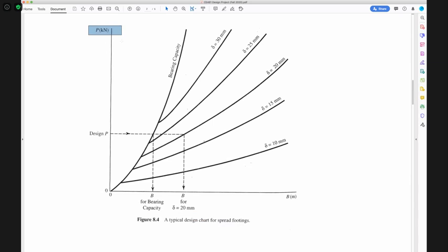We have a load for the foundation and the size that's required to hold that load. And we go through and solve that for bearing capacity. I mentioned in the problem statement just about a page ago that you'll want 10 data points to make this curve, the bearing capacity curve. So you'll come in with different loads around your design P. You know what that is, in this case, 110,000 pounds. So you'll have some that are below it and some that are above it, and come up with some representation of a design curve like this.